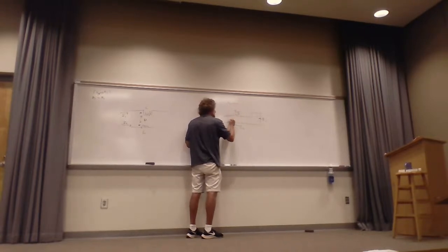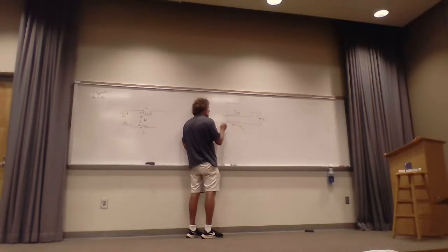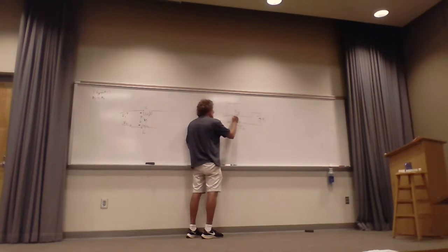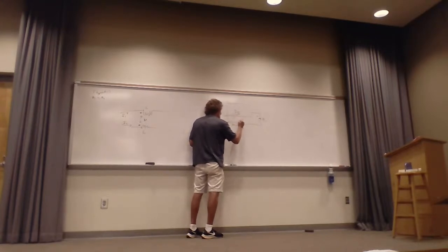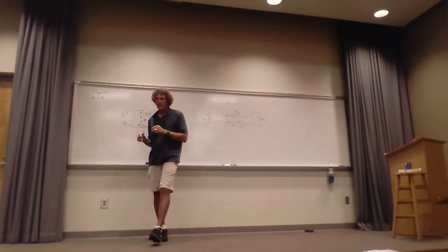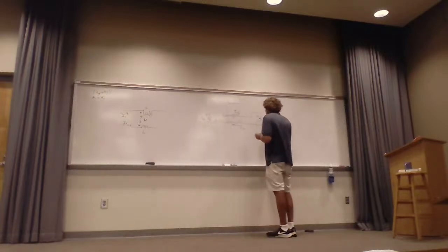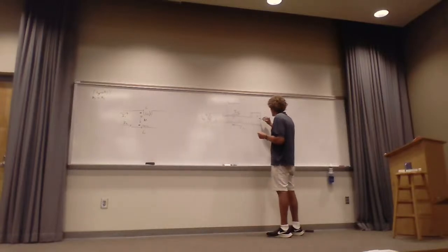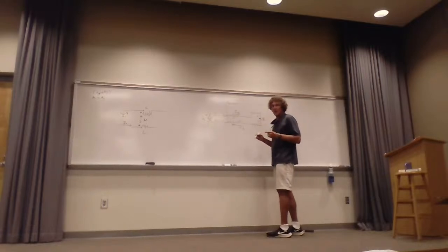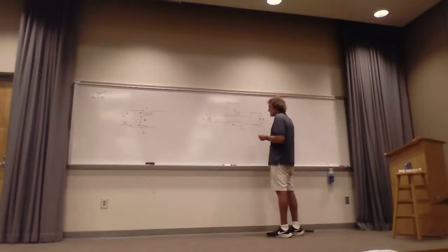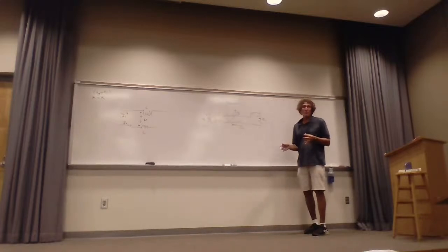Well, some of that goes this way, some of that this way, some of that this way. But the point is, this is going to be a common mode current that's flowing there. Y'all with me? Now, why don't you want that? Because when this is flowing down here, I'm not showing this to you, all this current wants to get to ground somewhere. And the way it gets to ground usually is it destroys something inside of that device to get to the actual earth ground. That's the reason common mode is bad.